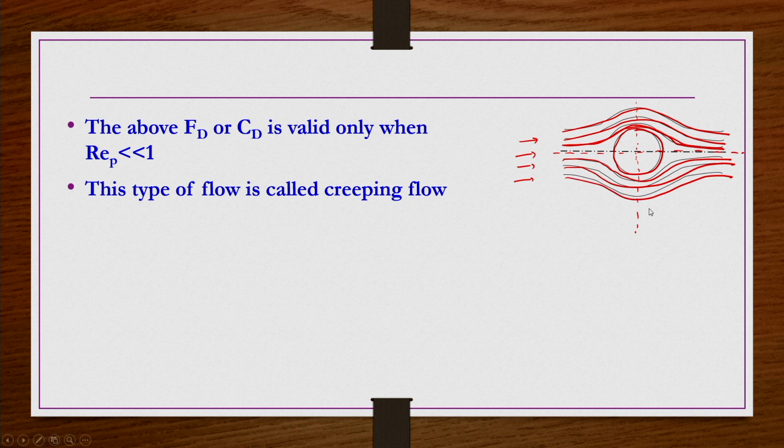So, that is the symmetry in either direction, left and right, that is fore and aft, and top and bottom symmetry of the streamlines we can see. The particles simply come, climb, creeping slowly like this, and then fall down slowly without being affected by the presence of these particles. That is how the streamlines look for the creeping flow conditions.